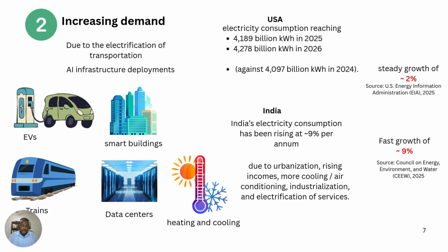So if you build a power plant, let's say a 100 megawatt power plant, and then you want to inject the 100 megawatt into the transmission network, you don't size the transmission lines based on 100 megawatts. Mostly transmission lines are oversized in expectation that there will be future expansion. So when there's future expansion, there's no need to change the transmission line because there's more capacity.